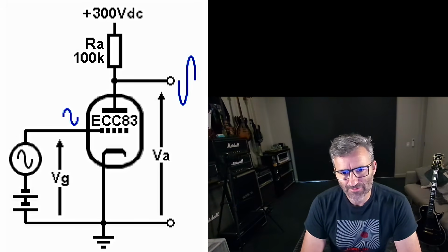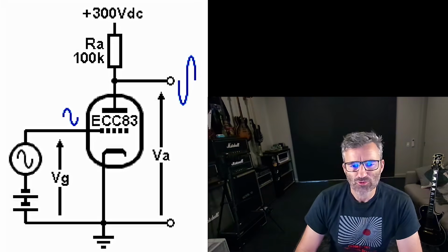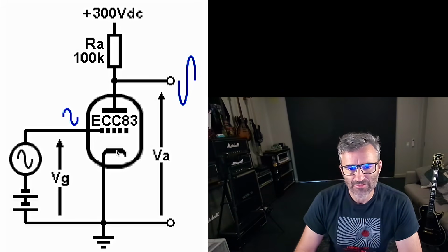So what we're seeing on screen here is akin to what you'd see in a fixed bias power amp tube, right, where you would have the cathode tied directly to ground. You'd have a negative voltage on your grid, right? So fixed bias meaning adjustable bias, right? You would dial this in with a negative voltage, right? So the grid is negative DC voltage compared to the cathode. And then obviously a plate voltage, right?